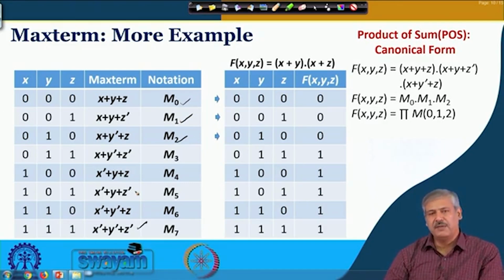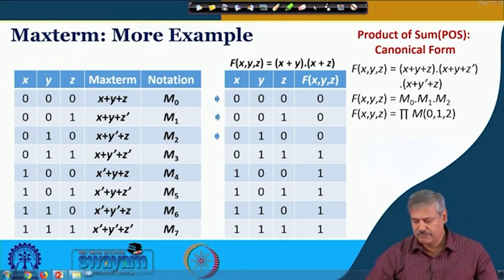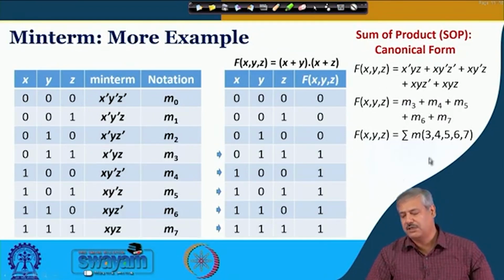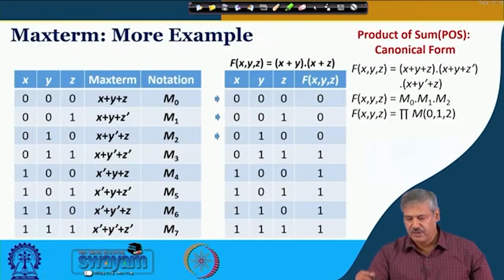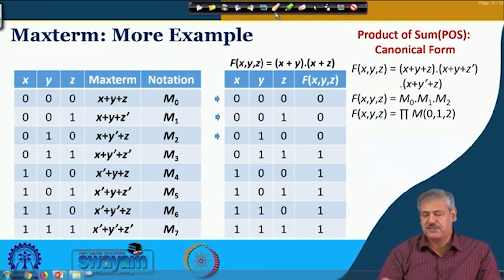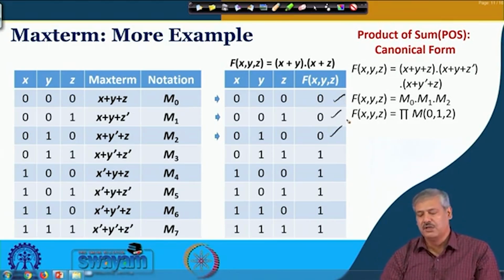Okay. For the same truth table that we had seen before, if you remember, we had 5 ones here, and the min terms contained 3, 4, 5, 6, 7. Now, we are trying to represent it using max terms. So, the max terms that need to be considered are the places where there are zeros. So, 3 zeros are there, 3 max terms will be there which will finally be ANDed. So, we have to see how each max term is represented.